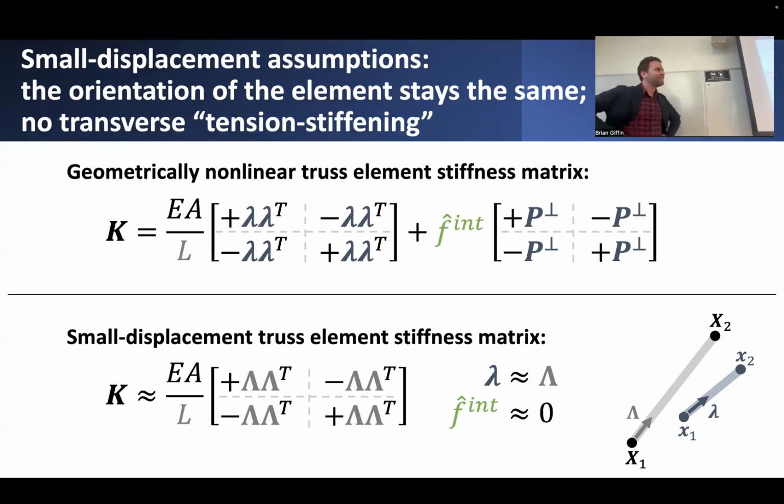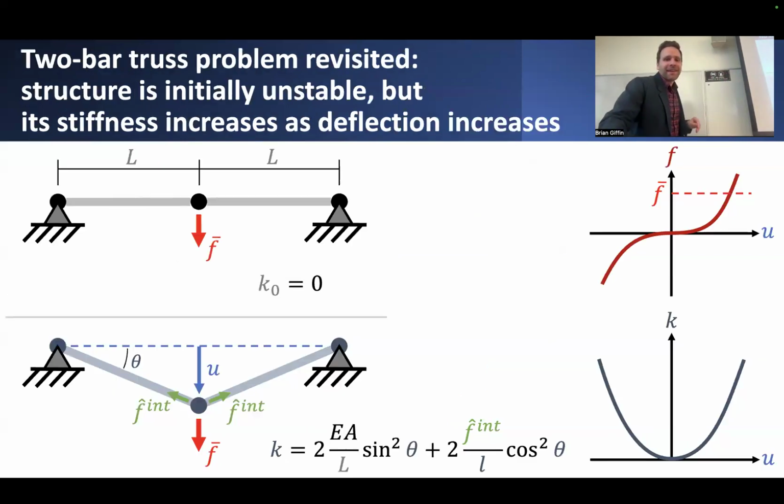This F hat term shows up in addition to our regular stiffness contribution, dependent on orientation. It's a force-dependent stiffness. As we increase the internal force in this cable as it's deflecting transversely, there's this extra stiffness contribution that makes the cable look even more stiff, beyond just the fact that as you deflect it further, there will be a component of resisting force that can go through these cables, which is not strictly horizontal anymore because the cable is sagging.